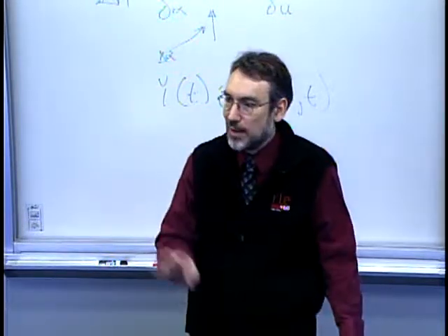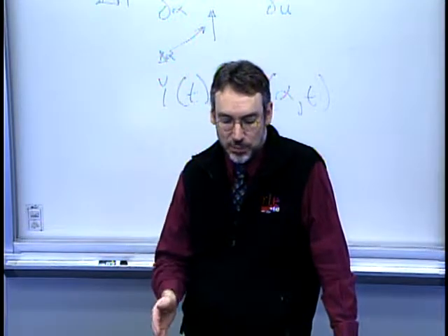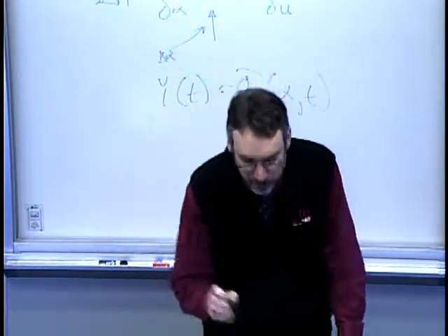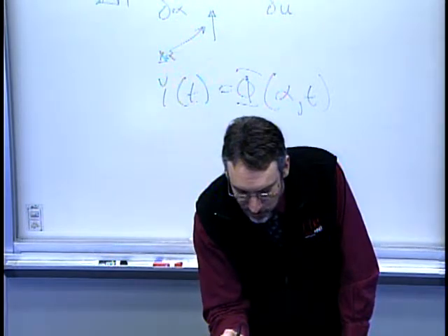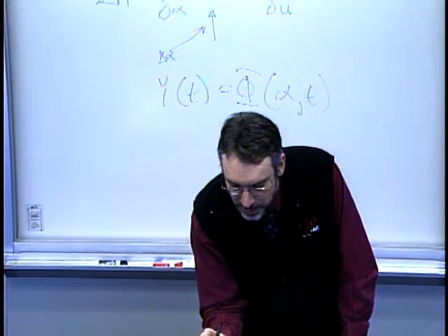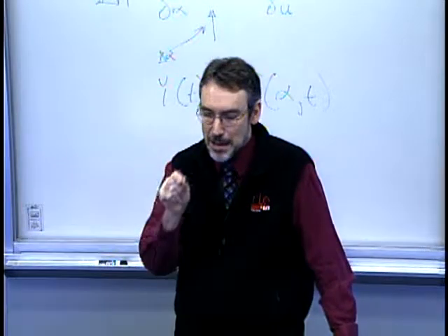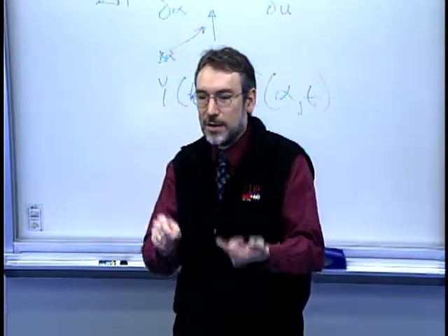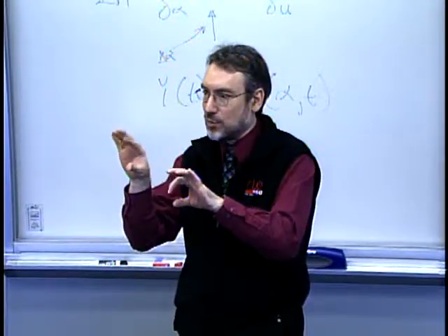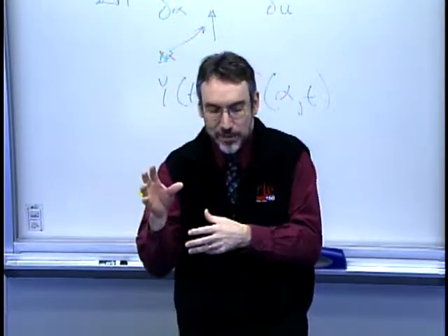So what are some ways that we can actually characterize and model the random components? Well, that's where we're getting into random processes and random variables. And I hope you're seeing this is the basis for statistical process control I've referred to, and we'll dive into some of the tools and techniques as well. Design of experiments. So if we were making that pressure change or that time change, how big of an effect is it? How certain are we within the random natural variation that the deviation or the controlled decision I made actually had a big effect.